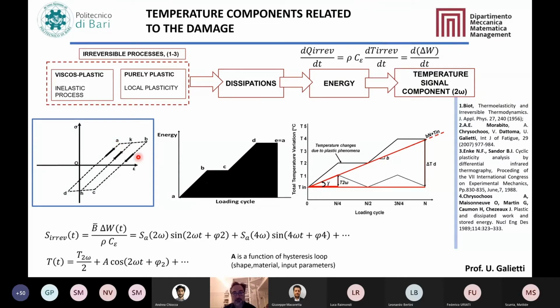But when we go to the plastic area, then we see an increase of the energy that we are putting inside the material. That corresponds to an increase of temperature of the solid body. Then again, in the elastic part we don't experience anything but the thermoelastic part, which is not represented here. Again, a change of the energy stored and dissipated inside the material, and again the elastic part. If we look at the temperature, this means that in a cycle during the fatigue load of the material, the temperature will experience a change in this way.